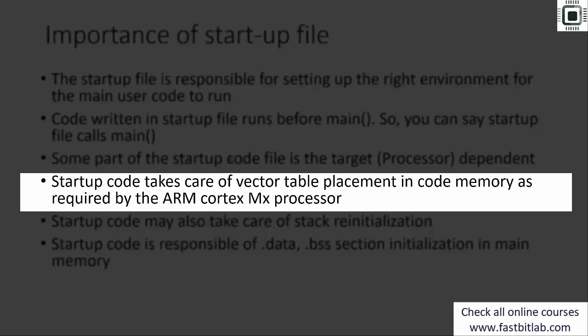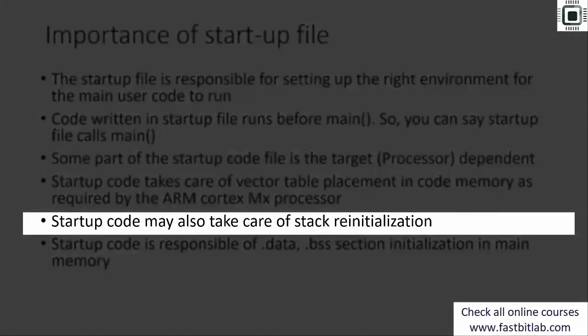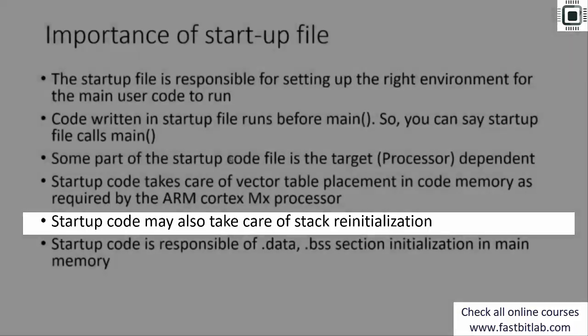Startup code takes care of vector table placement in code memory as required by the ARM Cortex-M processor. You know that initial code memory addresses have to be filled with the vector table, isn't it? That should be taken care of by the startup file. Startup code may also take care of stack reinitialization. I mean, you can alter the stack placement.